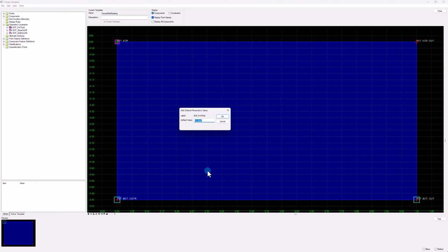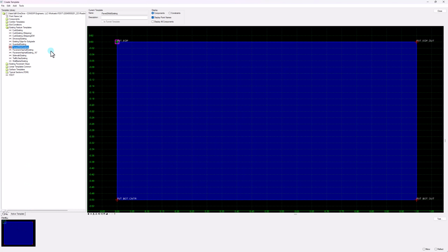So if you need to change that, you can go ahead and do that. Again, you might have pavement cores, or you might just be assuming some depth here for the existing pavement. I would say 6 inches is pretty good, and we can just keep using that. So now that we've taken a look at that, we can just go ahead and come back over into the library view, and we'll just be using this surface template going forward.